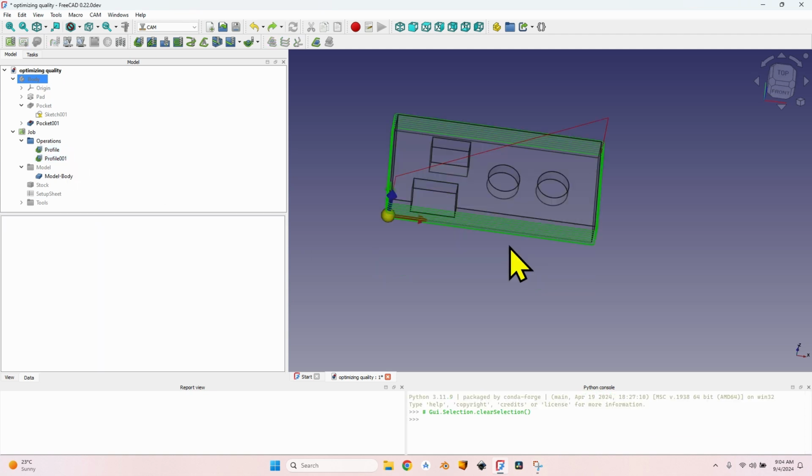I hope this video will help you get much smoother finishes when you need them, and of course in the case of the round holes, to get the correct dimension, the correct diameter, it is pretty important whenever, for example, you want to put a roller bearing inside the hole. If it doesn't fit or if it is too loose, it's a bad thing, so getting the correct dimension is essential. Of course, this depends also on your machine, but regarding the G-code, making it from the outside, as I've told you, most probably will fix those issues of the machine.